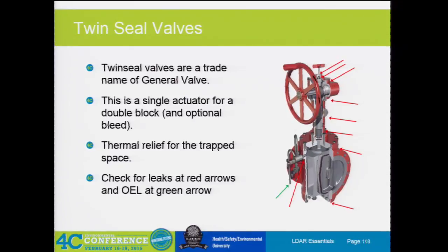As far as tagging and identification of the component, you'll see all these, and there's this valve here. Some people call that its own valve as well. You see it both ways. You see people saying that's part of that twin seal valve as a whole, or you see them call it out as a completely separate valve. Either way is fine, as long as you monitor all the leak interfaces, that's all you're required to do. So whether it's one valve or two valves, monitor everything.